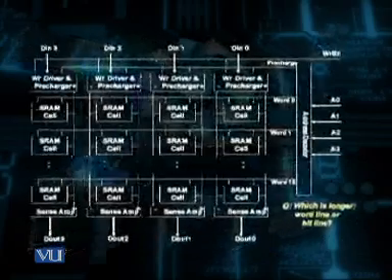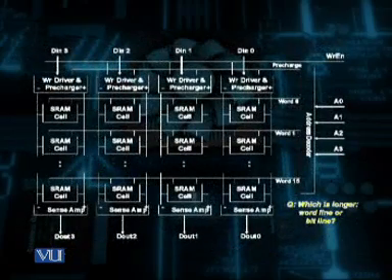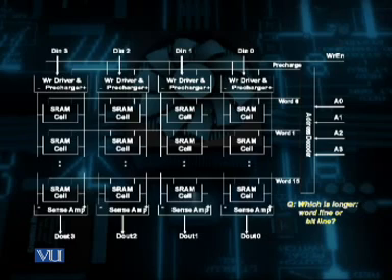Now let us see how these basic cells are organized to design a big RAM circuit. For this purpose, let us have a look at the design for a 16 by 4, which is a 64-bit RAM. This means that it consists of 16 words, and each word in this case is of 4 bits.